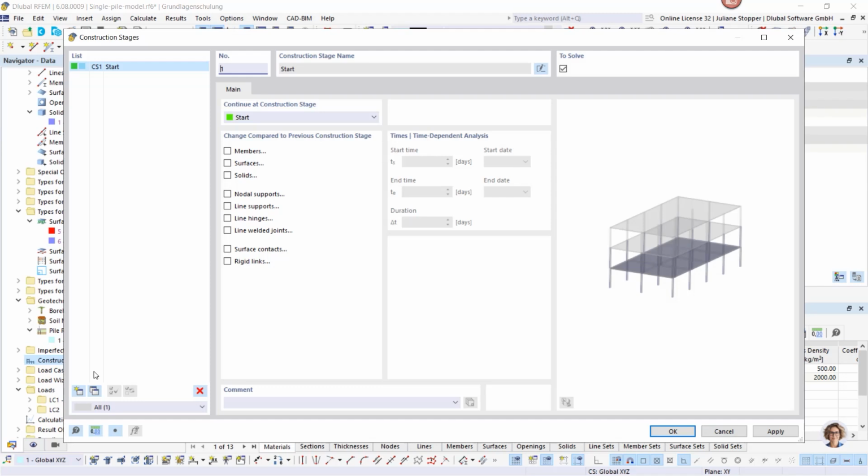So that's why we use it for the hardening soil, for having the deformation of high quality in the analysis for the soil. So the first stage is stage 1, and I would like to give it a name. It helps with having the overview on the phases. It's our initial phase. This is for calculating the stress from soil self-weight, so that we can afterwards use the correct stiffnesses.